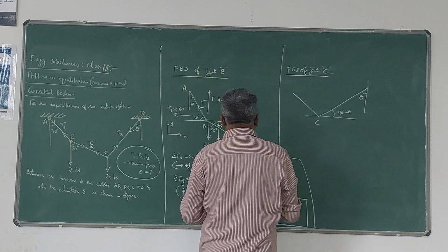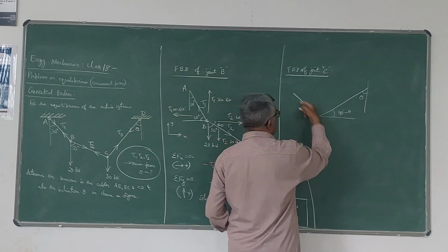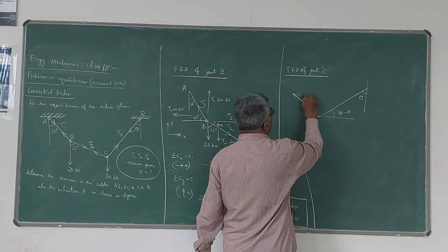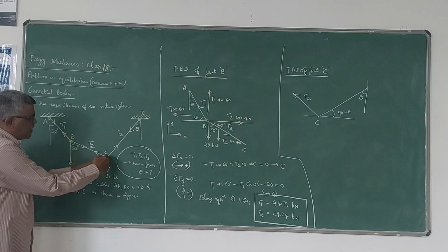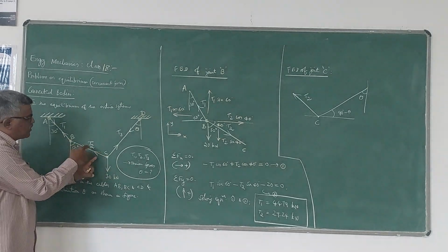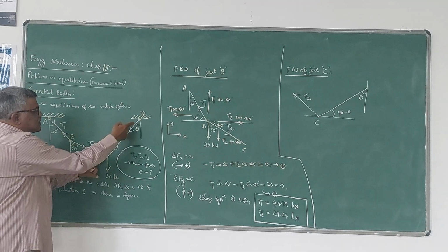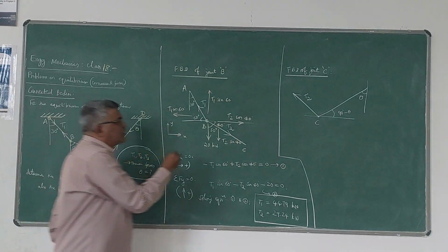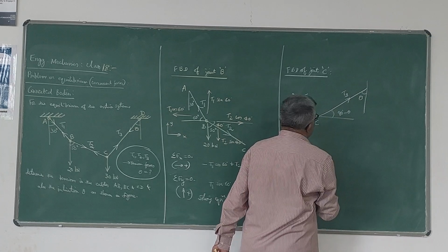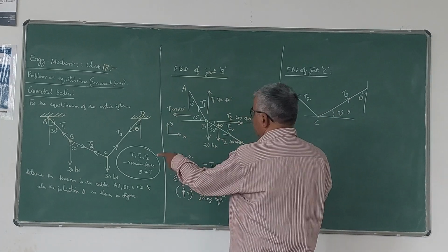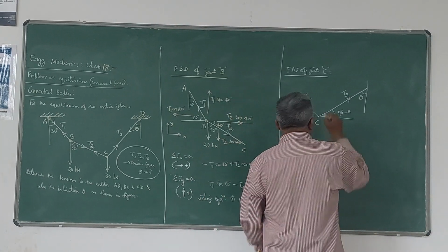And the forces, tension force, away from C we have to take. This is P2. Please see here. So this is joint C. Away from C, in the direction CB, you have tension force P2. In this direction, we have a tension force T3. So this is T3, like this. So here, T2 already you know. T2 value we have found out. It is equal to 29.24 kN.